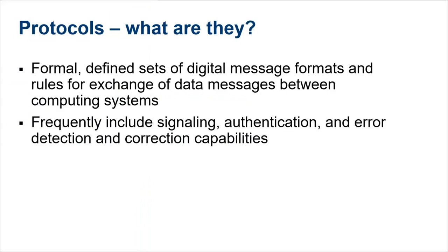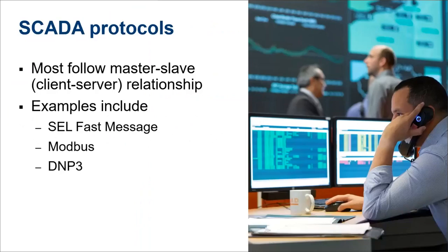So this is often for signaling, authenticating data, and detecting. The protocols will define how to detect errors and correct the message and data sent. A common term around protocols is SCADA, supervisory control and data acquisition. Most of these protocols follow a master-slave or client-server relationship. The ones that we'll mainly be covering today are SEL Fast Message, Modbus, and DNP3.